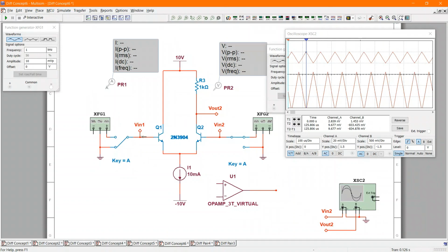And then VN1 over here, that's going to cause an in-phase output. So that becomes the non-inverting input. That has a plus sign on it. So we would not draw this whole thing in a schematic. We would draw this where VN1 would go to the positive, VN2 goes to the negative, and then the output is a single output.